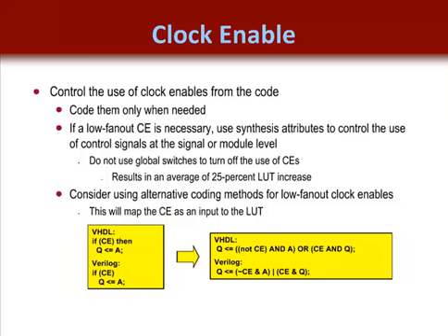Synthesis tools will get smarter about when to use the dedicated clock enable control signal port and when to move the clock enable function to the data path, but unfortunately it's going to take some time. You should also note that some synthesis tools allow the user to disable the use of a clock enable port on the register. Xilinx does not recommend this use, typically because on average it results in the use of up to 25% more lookup tables.